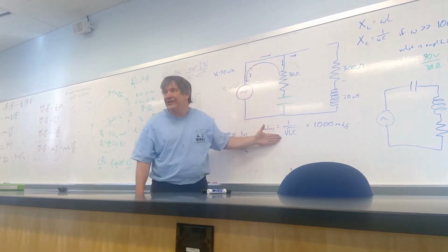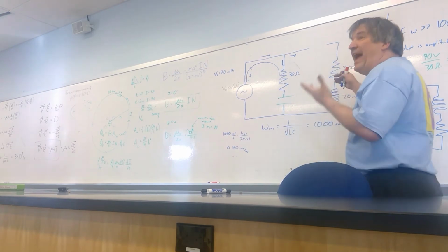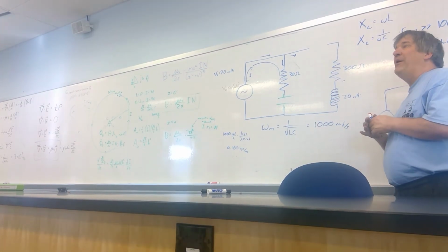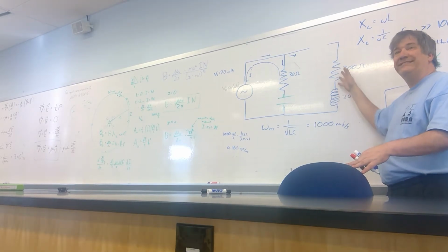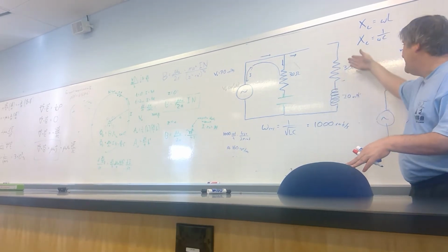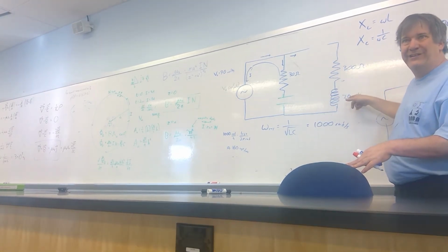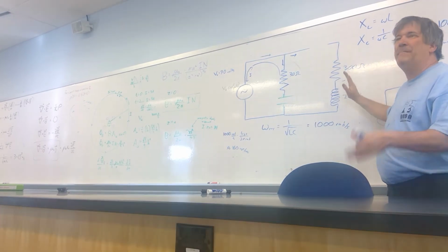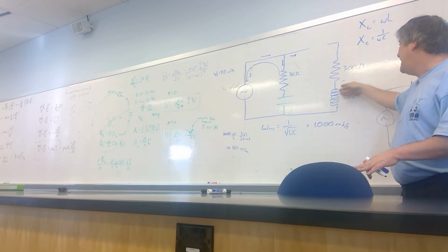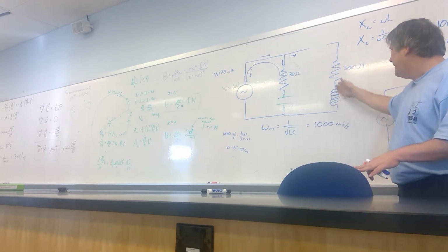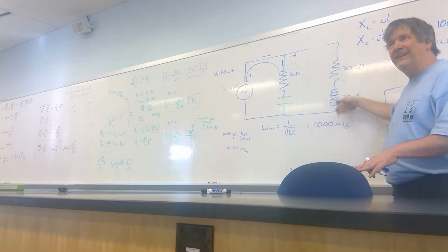It shuts down current through this branch, while at low frequencies, the inductor acts pretty much like a straight wire. Now, again, a real-life physical inductor might not, because it would also have some resistance to it. So in fact, this whole branch of the circuit could actually just be one device, but the way I've drawn it into my circuit is I said it acts like both a resistor and a perfect inductor in series with each other. But at least my idealized inductor here, at low enough frequency, has no voltage drop across it. It's acting like a wire.